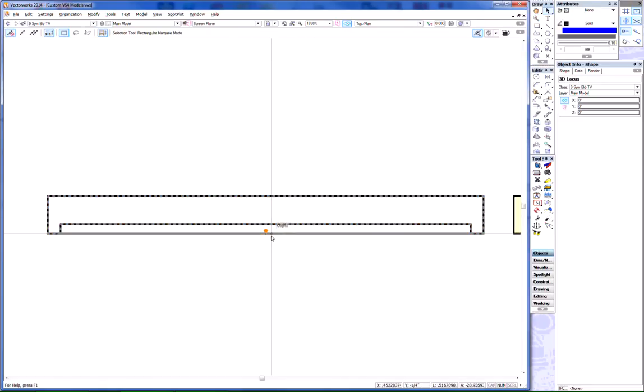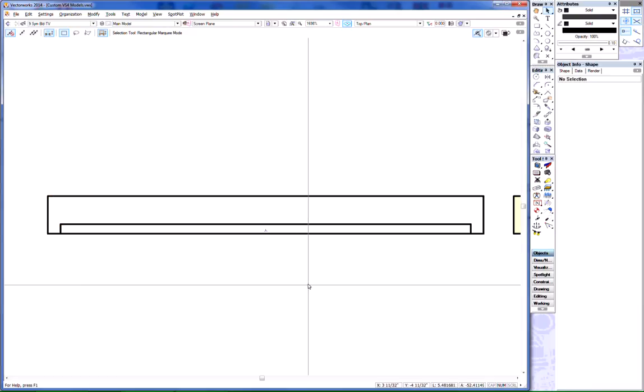The other thing that I want you to see is where I've got what's going to become our origin located. If I snap to it, the cursor will show you where the screen is going to end up. Now you'll notice that it's recessed back a little bit into the shell. That's quite intentional. So if you create a television symbol and you want your screen recessed, the front face of your television will need to be in front of your intended insertion point.